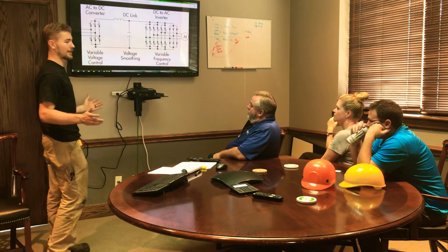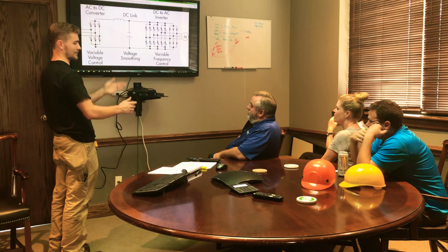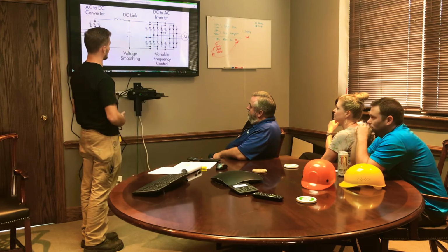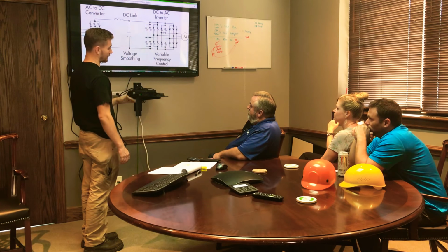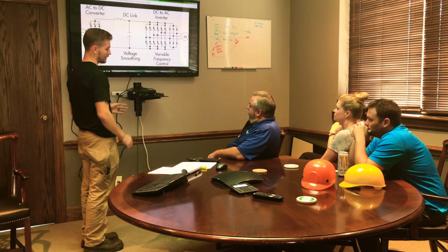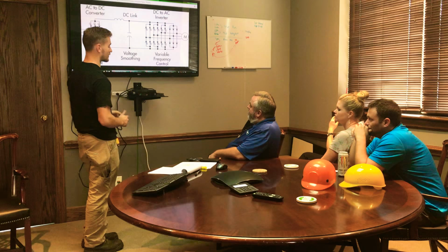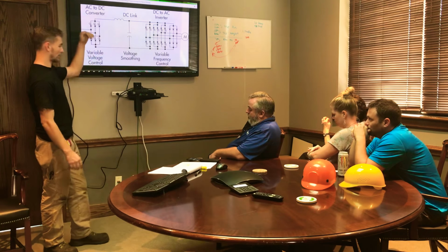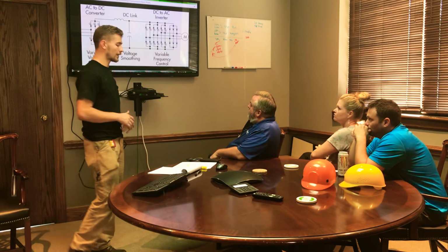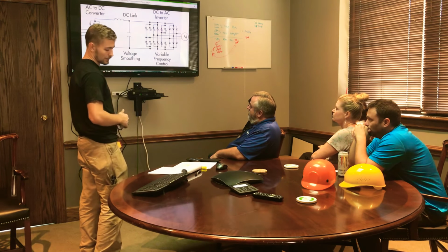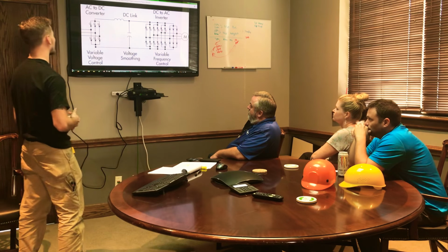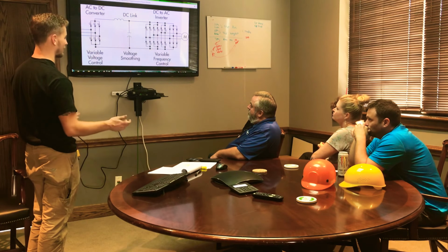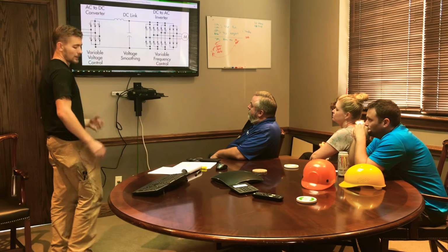At that point, your motor's probably just going to be humming because it's not polarizing those magnets fast enough to actually spin the motor. It is important to note that this will come out in a rectangular waveform because these are not variable resistors, they're just switches, so it's either positive or negative. But motors do not care. They will eat up a rectangular waveform all day, whereas your household components, they will care. So in summary, the DC to AC inverter just outputs that DC back into AC at the frequency that is required to make the motor drive at the speed that we want it to drive at.